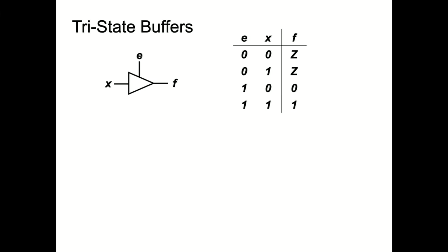If you connect F to something else, then yes. Okay. And this is called high impedance value. And of course, in Vivado, you cause this by just not specifying a value for a net, right? But you can do this intentionally, and there are reasons why this is useful.